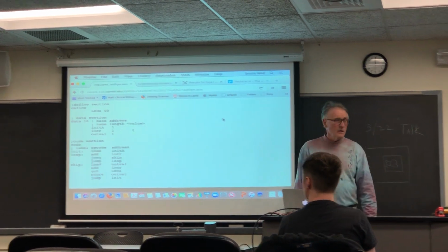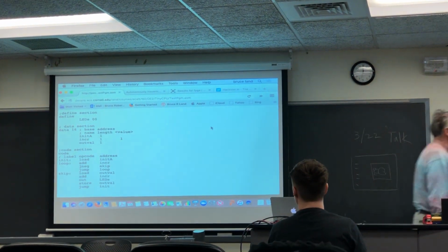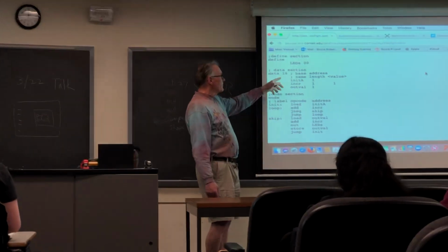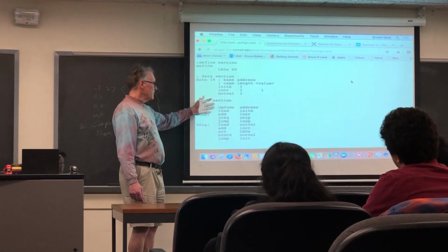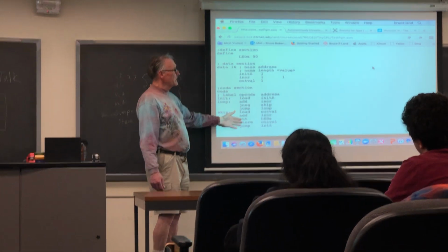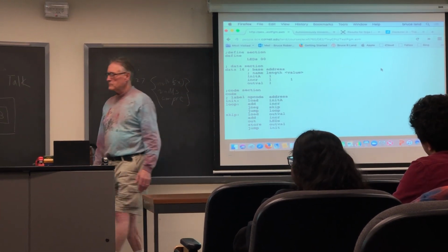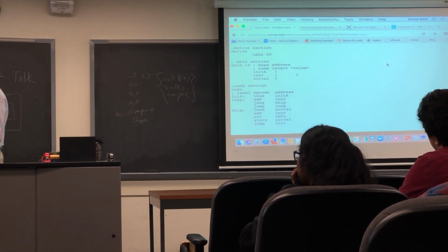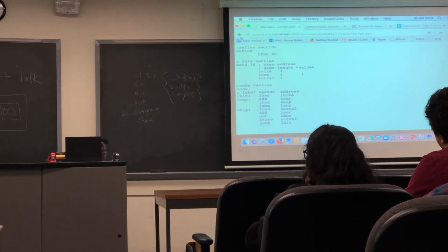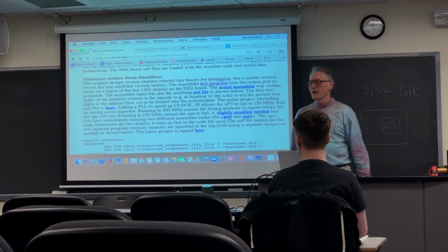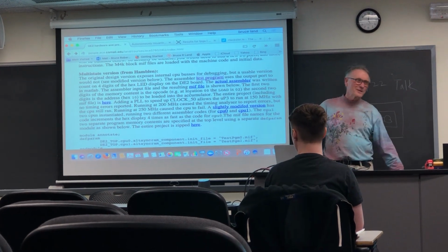So you can define constants, you can define data storage with a base address, and you can use a symbolic assembler. It compiles to M10K blocks. So you can make as many CPUs as you have M10K blocks, if you want.